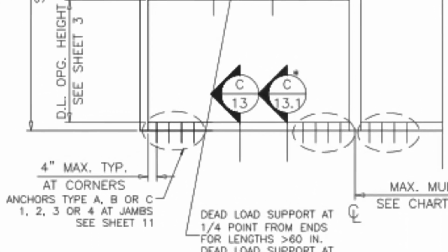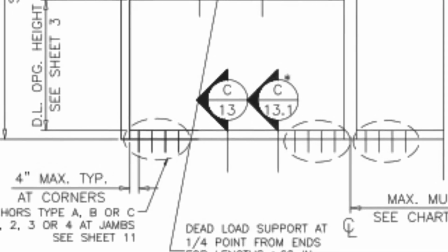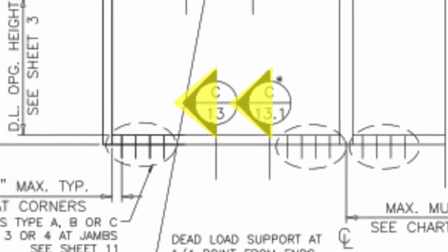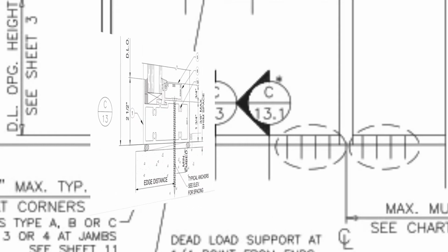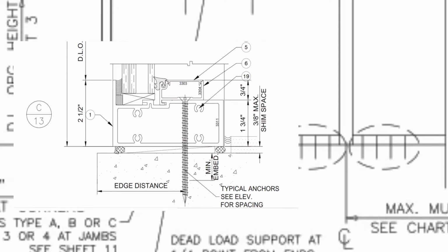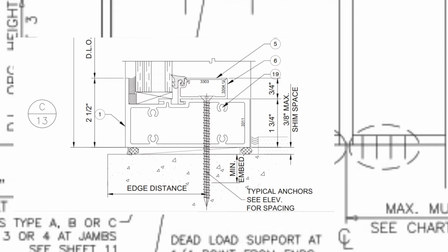Now you'll notice there are symbols all over this drawing. The symbol is a black triangle with a white circle on top of it so that you can't see most of the triangle. And then that symbol has, extending from the triangle, a little black line, and that black line doesn't extend out a very far distance. Now that's a symbol that's telling us there's another drawing that corresponds to the location of that black line, and it's drawn from the perspective looking in the direction that the black triangle is pointing.